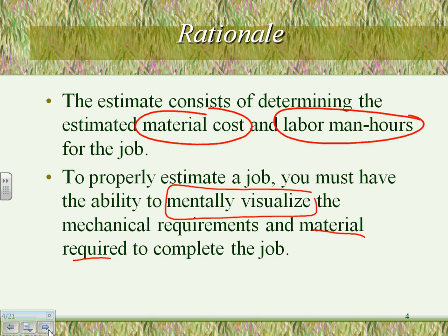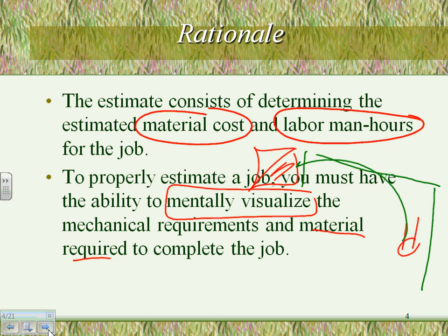If there's an outlet right here, and a panel right here, and this panel is circuited to this outlet, you have to understand that you have to go up, over, and down again to this panel in 3D. Very, very important.